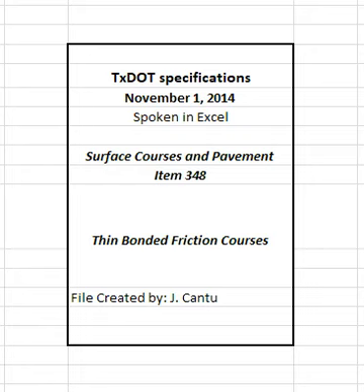For material delivery and storage, include the sequence of material processing, delivery, and minimum quantities to assure continuous plant operations. Aggregate stockpiling procedures to avoid contamination and segregation. Frequency, type, and timing of aggregate stockpile testing to assure conformance of material requirements before mixture production, and procedure for monitoring the quality and variability of asphalt binder.